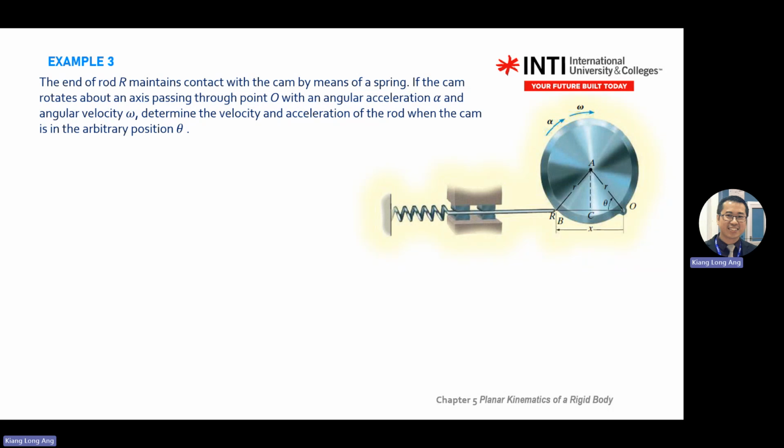It tells you velocity and acceleration, not angular velocity and acceleration. So when you see normal velocity and acceleration without angular, link back to these two equations on the whiteboard. Velocity V equals omega R. Acceleration has two components, tangent and normal direction. So AT equals alpha R, AN equals omega squared R. When the object moves in a straight line, you only see the tangent direction. There's no more normal direction. If you don't understand this, go back to chapter 2 slides.